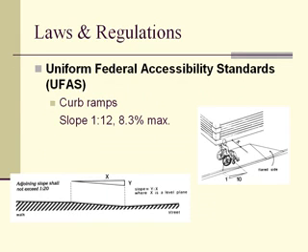Nothing says that we can't design and build these elements with a lesser slope. And actually, the requirement calls for the least possible slope. So many times we will see that some elements are right around the requirement, but they shouldn't be. When we have a requirement that sets a maximum, we should design well below it so that these elements are fully compliant. Otherwise, if we design exactly at the requirement, it is likely that we can fail and the elements will be non-compliant.